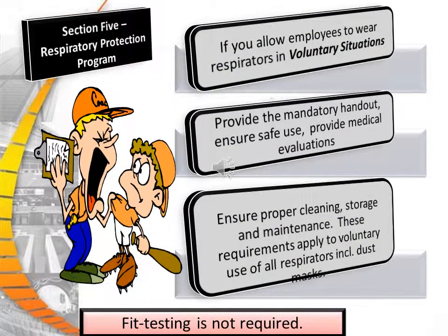If you allow employees to wear respirators in voluntary situations, they must be provided with a mandatory handout to ensure safe use, and provided medical evaluations. You must ensure that proper cleaning, storage, and maintenance occur, and these requirements only apply to voluntary use of respirators. Fit testing is not required in voluntary situations.